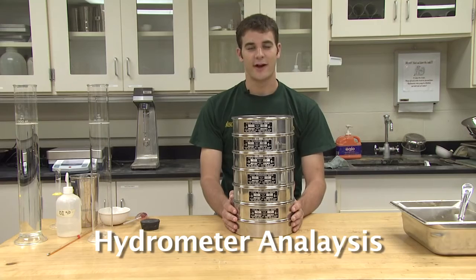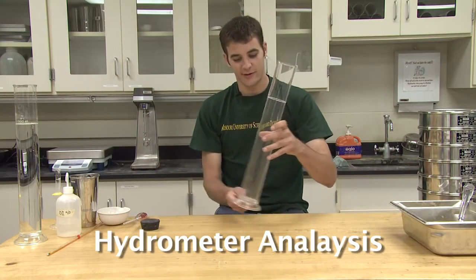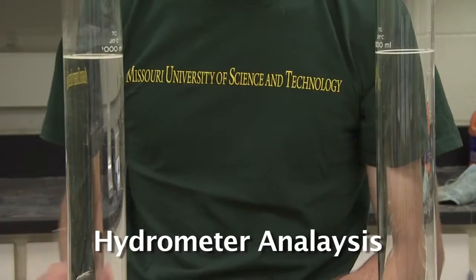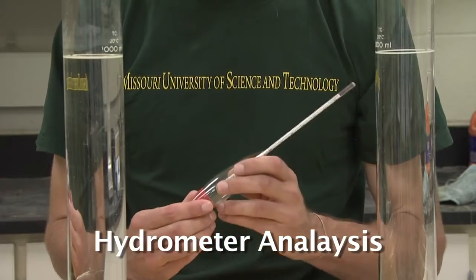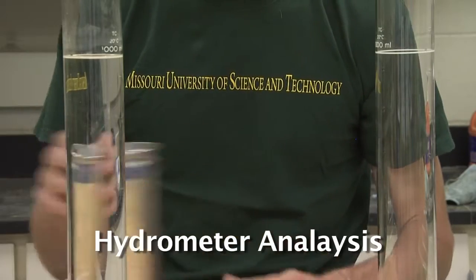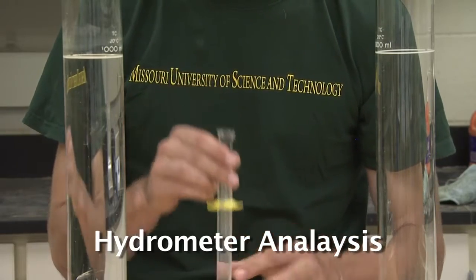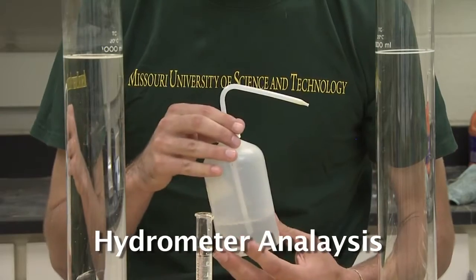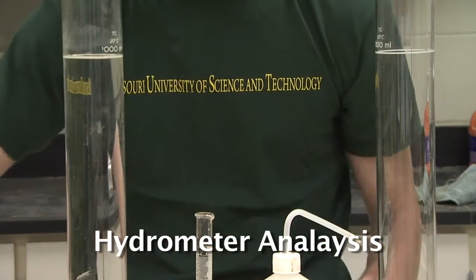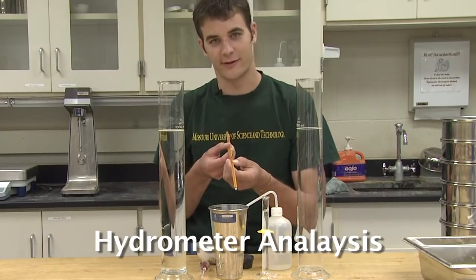In order to conduct a hydrometer analysis, the following devices will be required. A 1,000 milliliter sedimentation jar, a 1,000 milliliter control jar, an ASTM 152H hydrometer, a soil dispersion device, in this case a shake mixer, a soil dispersion agent, in this case sodium hexametaphosphate, a squirt bottle filled with water, an evaporation dish, a rubber stopper, and a thermometer measuring in Celsius.